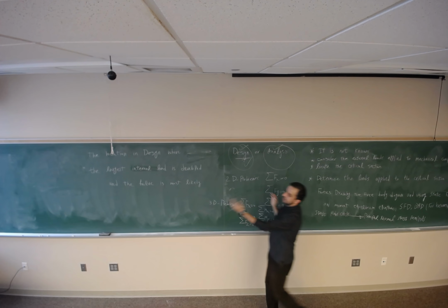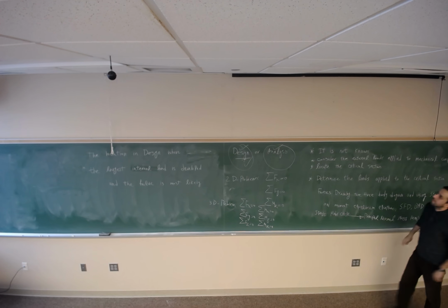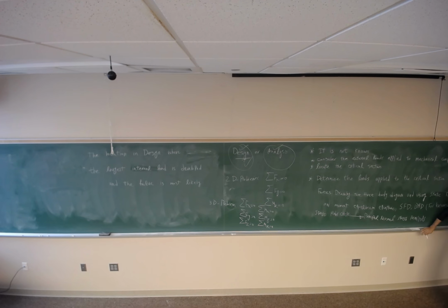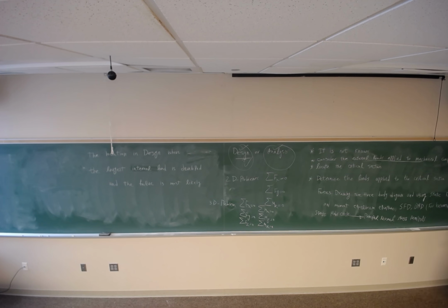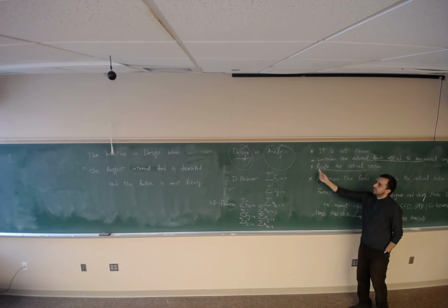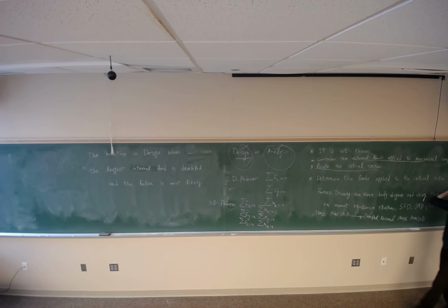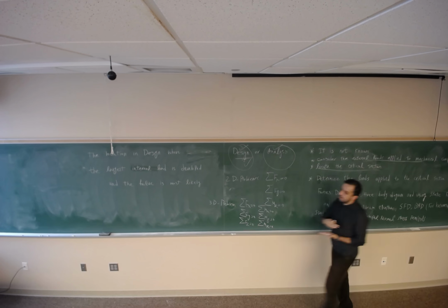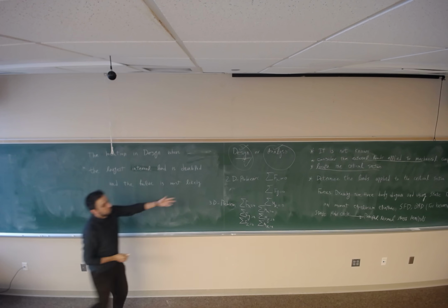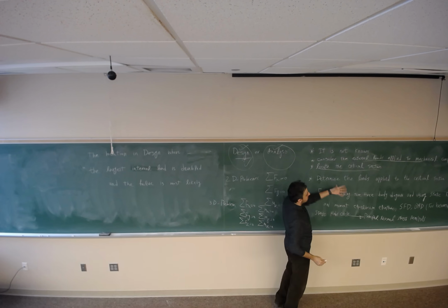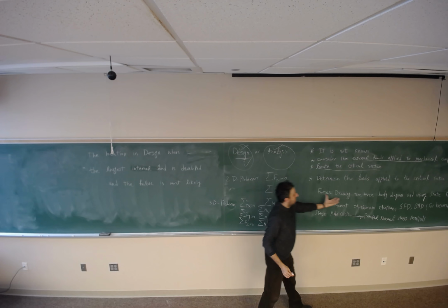By looking at the component, you don't know where the critical section is, but by considering the external loads applied to the component, you can figure out where the critical section is. After you figure out the location of the critical section, you determine the loads applied to it. So the loads, I mean the forces and moments, first. How can you find that?